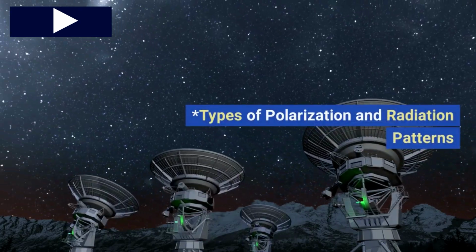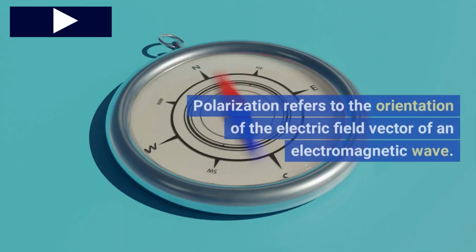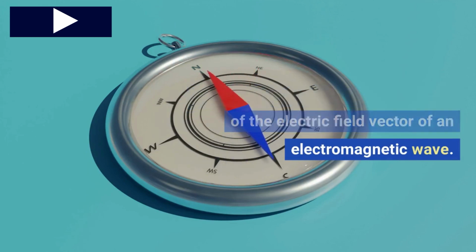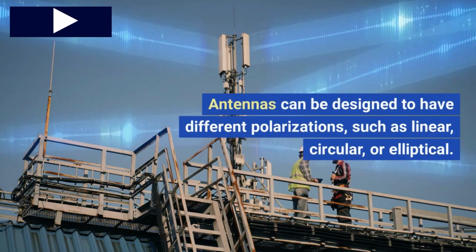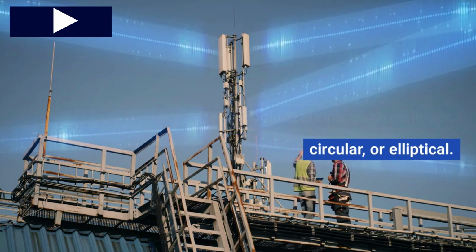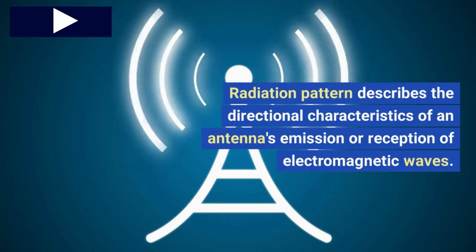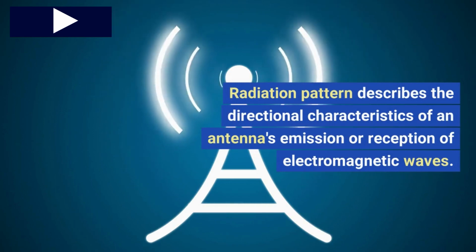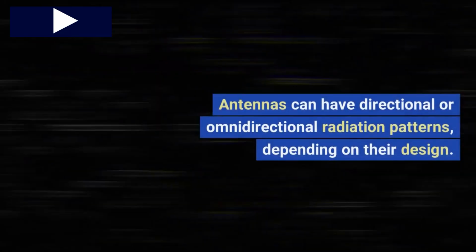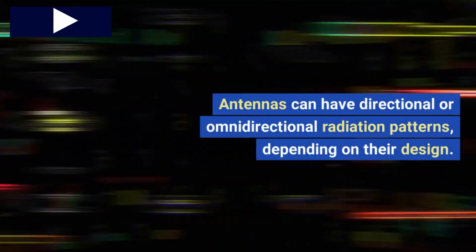Types of polarization and radiation patterns. Polarization refers to the orientation of the electric field vector of an electromagnetic wave. Antennas can be designed to have different polarizations, such as linear, circular, or elliptical. Radiation pattern describes the directional characteristics of an antenna's emission or reception of electromagnetic waves. Antennas can have directional or omnidirectional radiation patterns, depending on their design.